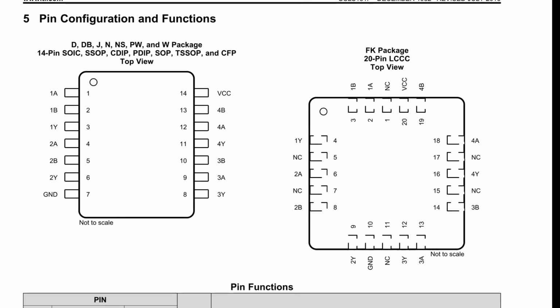So you've got your typical pinouts. You've got your pin 1 identifier up here, and unless they say, well, yes, they do say here, top view, so looking down from the top of the chip. Don't make the mistake of getting that back to front like you often do on these surface mount leadless chip carriers.